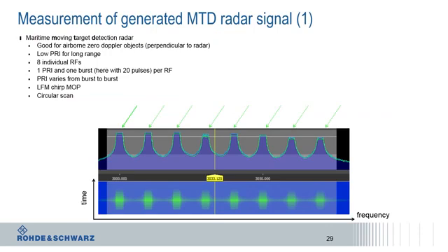Here are the details of the maritime radar and its signal. In the spectrum, you can clearly see 8 different RF signals. They are not on at the same time, but they are agile, so they are hopping. The power level is varying over time as there is an antenna scan involved. That's why you can see a max hold in the figure below and the green line, which is giving you the current or actual power level. Let's have a closer look.